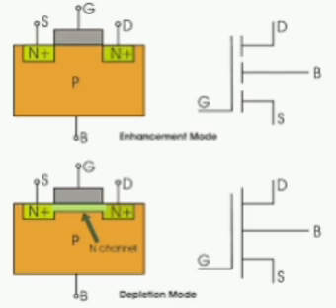If C minimum is known, maximum depletion width WD max can be found. C minimum equals C0 CD minimum by C0 plus CD minimum. CD minimum equal to epsilon SI into A by WD max. WD max equal to epsilon SI into A by CD minimum, where epsilon SI means silicon permittivity. CD minimum means minimum depletion layer capacitance.